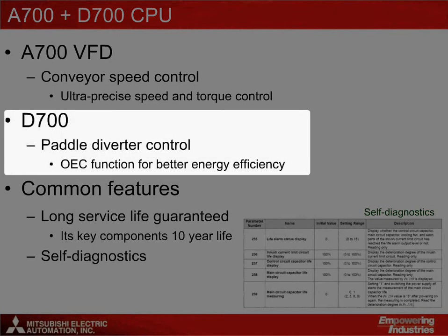The D700's duty within the application is to drive the paddle diverters. The drive's straightforward wiring, integrated digital dial with LED display, and integrated emergency stop function make the D700 perfect for simple tasks such as the paddle diverter control. The D700's OEC function helps to further optimize current and hence power consumption of the motor. The result is an additional decrease in energy requirements compared to conventional drives.